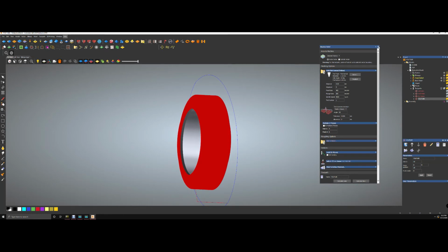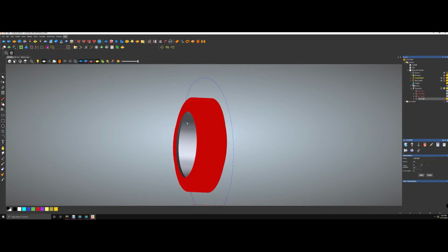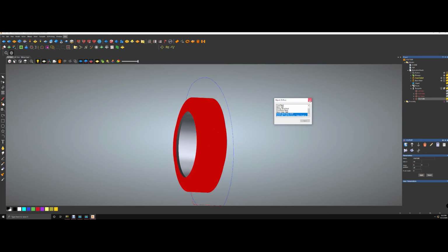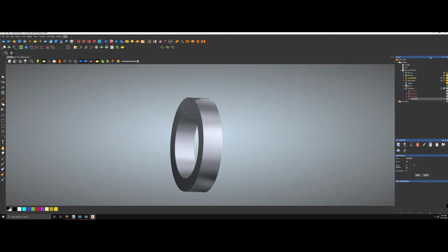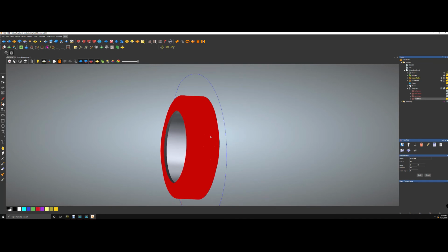All right, so we're going to close this. So we have the toolpath here. It's already created. I'm going to show you how you shut this toolpath off. By going here, you'll be able to see all these things here. You could just click the conical here, apply. You could shut her off. You could turn it back on, or you could shut her off here and turn it back on. Okay, let's open this up a little bit. You could move it, right? So let's park this here. These are your options here. You could turn it on and off, but you want that toolpath on. So I'm going to select it. You can see it's right here. I selected the actual tip or the drill bit.